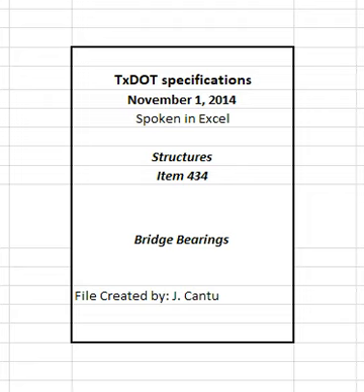Perform check tests if necessary on the steel, laminated elastomeric bearing pads, or PTFE material to verify the properties required under Section 434.2.2, Sliding Elastomeric Bearings. Bearings represented by test specimens passing the requirements of this item will be approved for use in the structure, subject to on-site inspection by the engineer for visible defects.